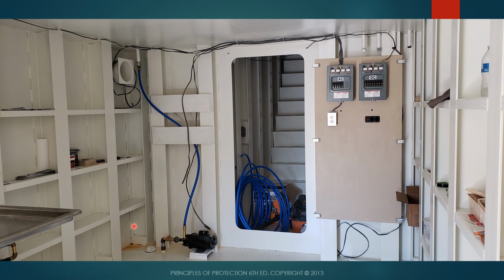By the way, when I was testing this and I took this off, that 4-inch hole shot that water up and hit the ceiling. And it's really hard to get that pipe plug back on there again. That is really hard. And one critical thing, don't ever forget this valve. If you don't put that valve in there, the water will go right through this pump. So be very careful about that.